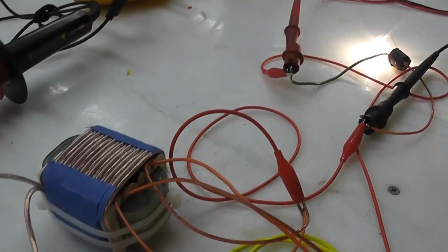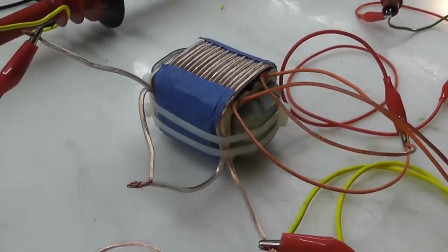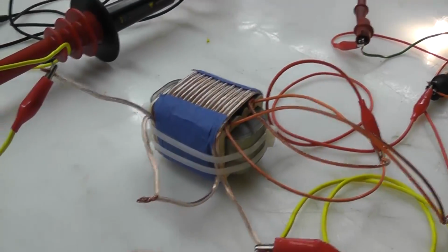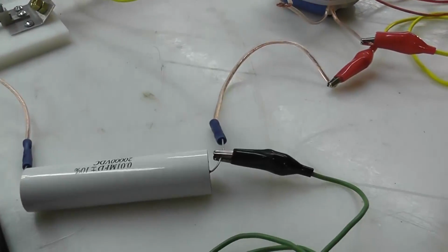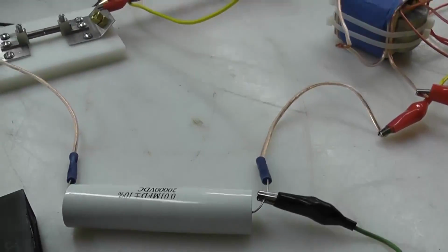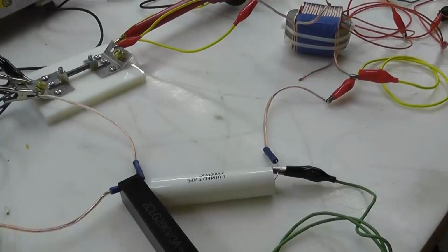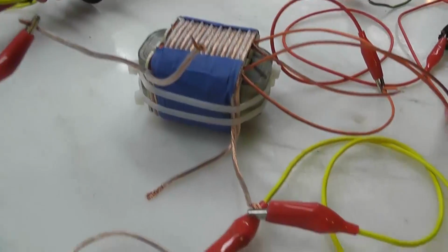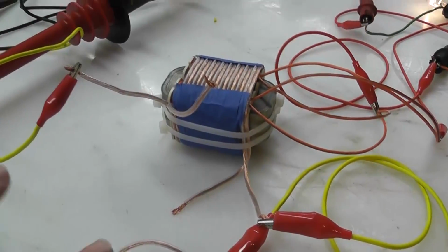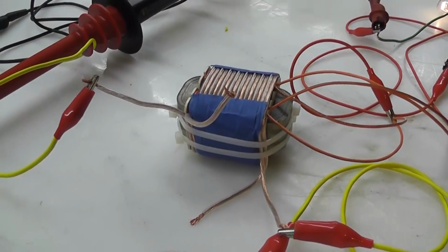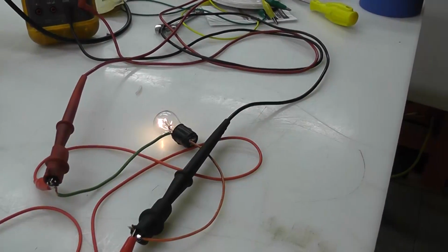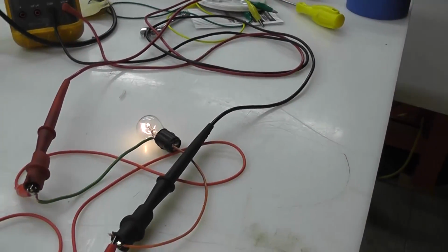So now I'm going to take this wire off here and hook this up how you see in that picture, and we'll leave this capacitor for now, might as well. So let's do that. And we're back again. So all I did is untie those two together and connect the main power across the two ends there, so it's not connected in bifilar anymore. Now the light bulb is very dim. It's probably the same as it is when it's connected to the 12 volt power supply.